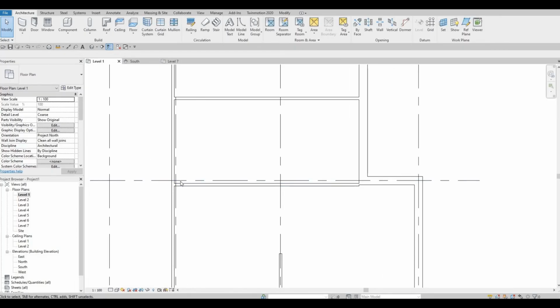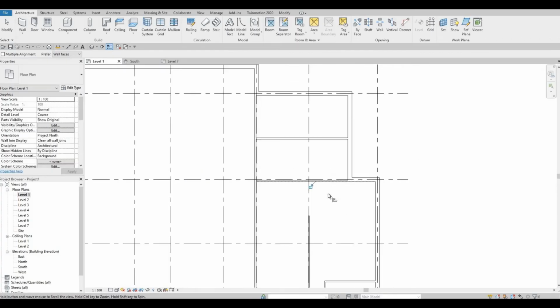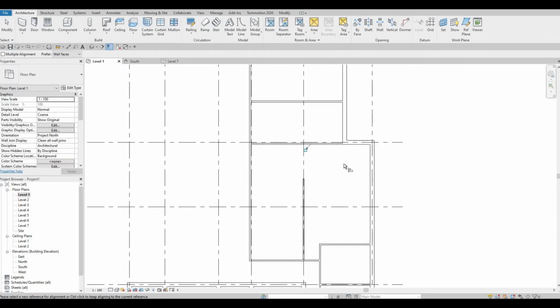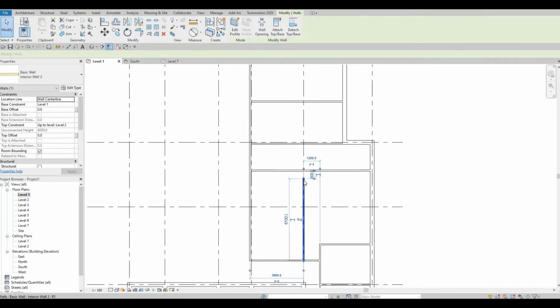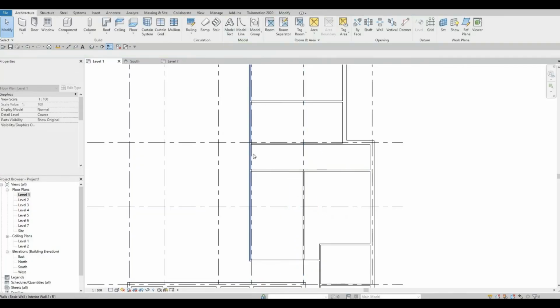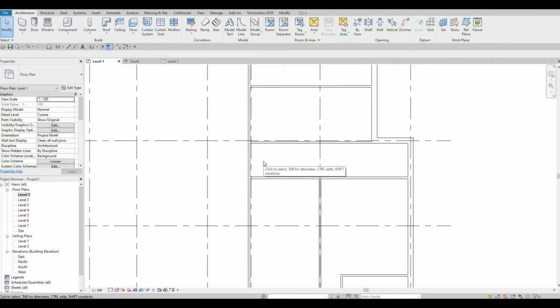And then click and close this off again, AL, to align it. This area will be the copy area. So I'm just gonna add in like that. Pull this up. I will type in SL. So like that, and then trim, TR, and we have our copy area here.